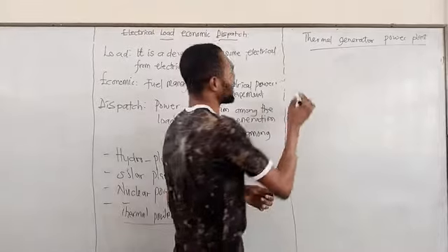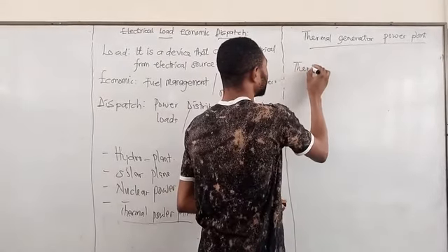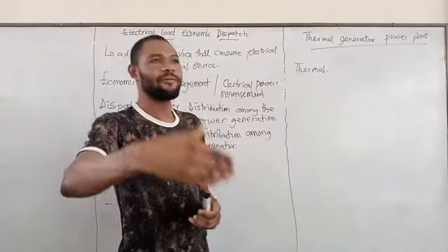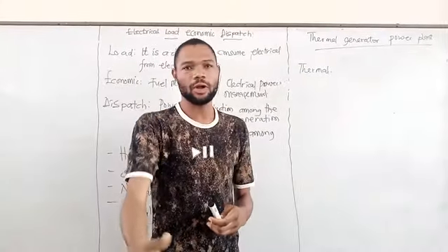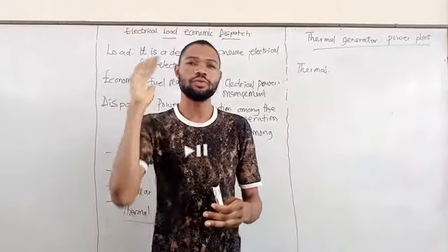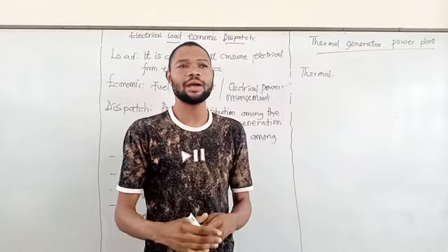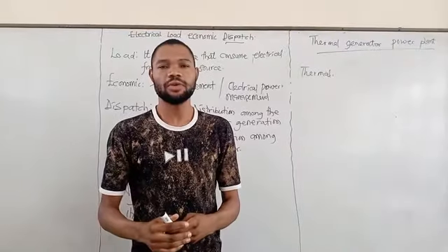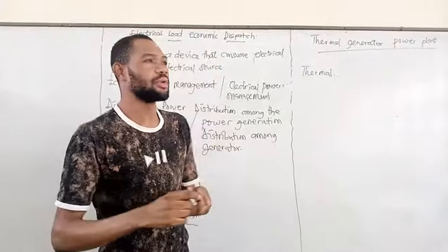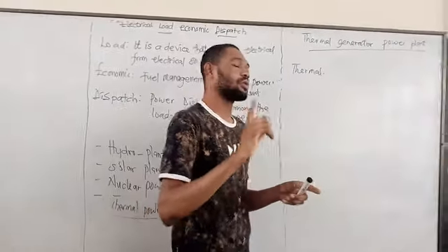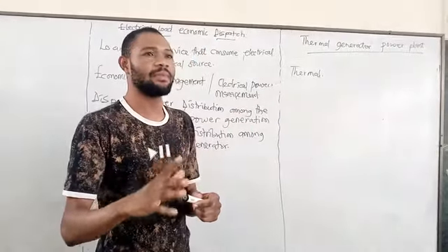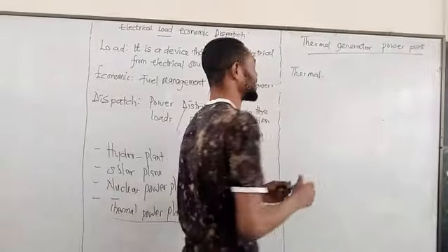When we are talking about a thermal plant, basically we are talking about burning a liquefied or fluid fuel to make steam, and that steam is then used to turn the turbine of the generator. As the turbine has a rotor coupled to the generator, as the turbine turns, it causes the rotor to rotate among the windings of the generator, and EMF is induced. So that is what basically we are coming to see.